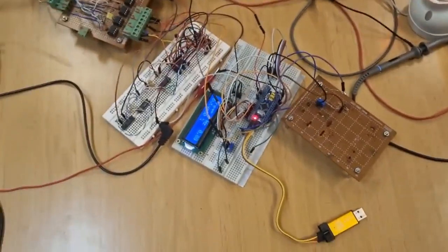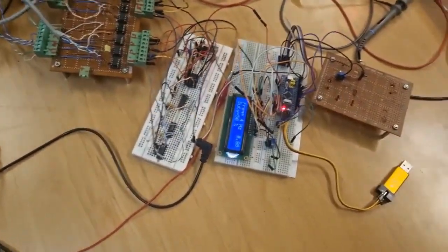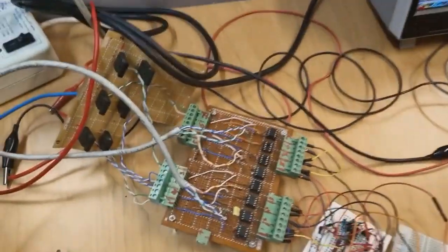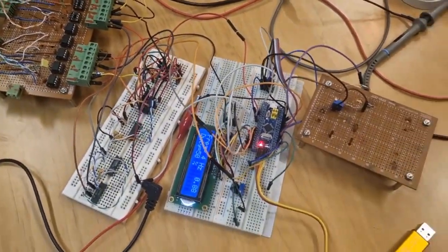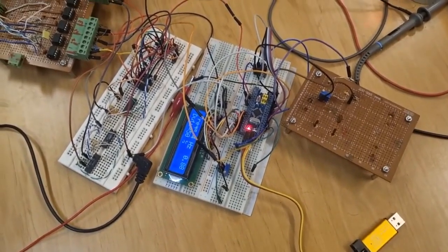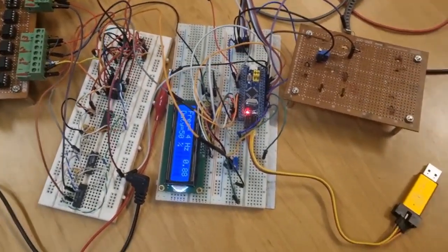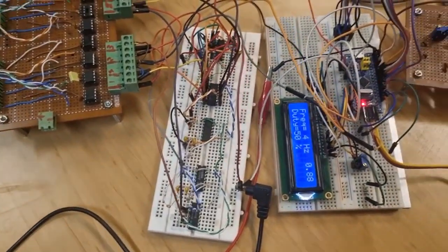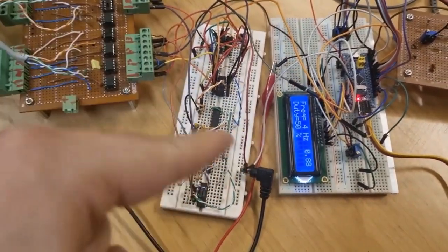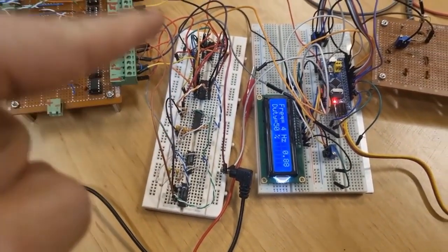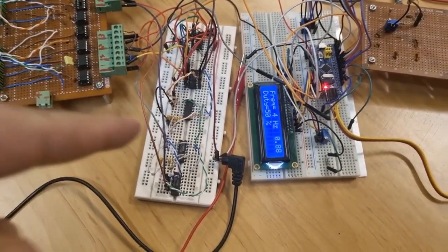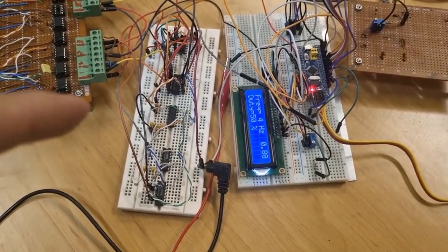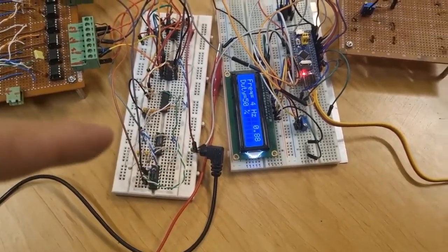So, in this project, I became acquainted with this 3-phase inverter, and especially with how to program a microcontroller to create 3-phase signals, and designing a dead time generator. And this circuit, you can see here, can create 6 signals with dead time, 2 signals for each leg with dead time, and that's it. I hope you enjoy it.